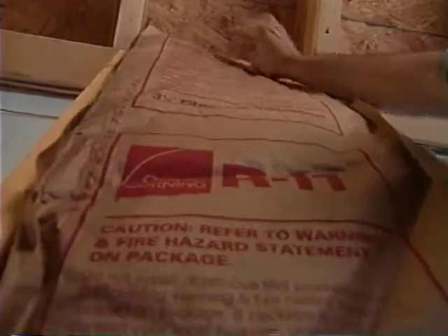For instance, in a wall, if you've installed bad insulation and compressed it in so there are passages between the sheetrock and the paper facing, then as the air in that cavity heats up, it's going to rise, pull in cold air, and you're going to lose heat out the top. And if that's a significant amount, it can really cause a comfort problem in the house.